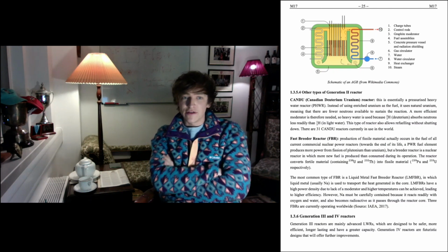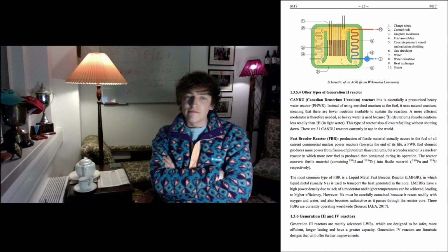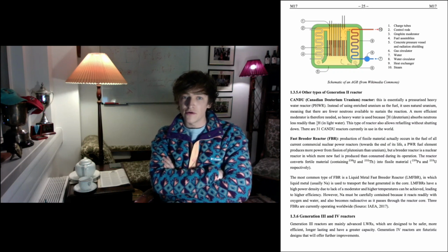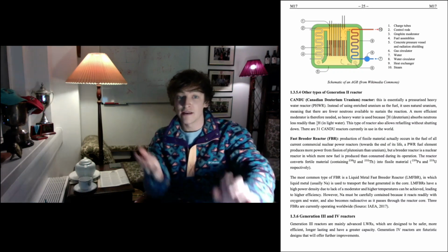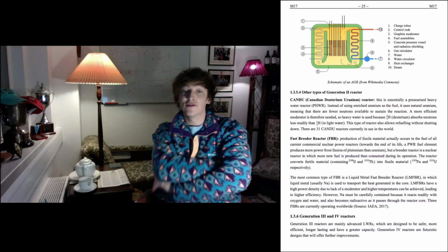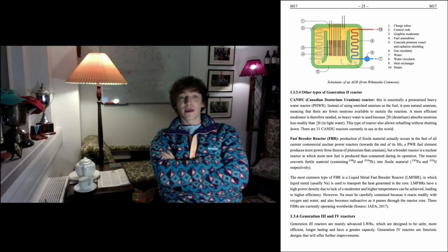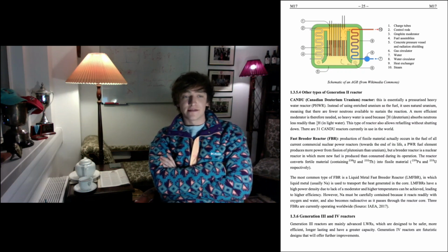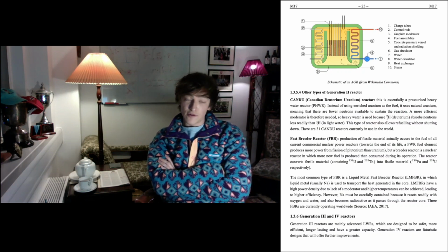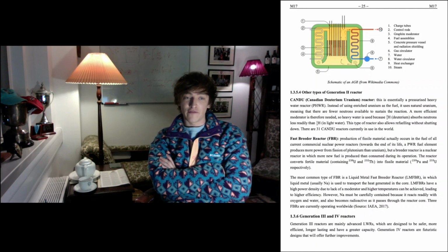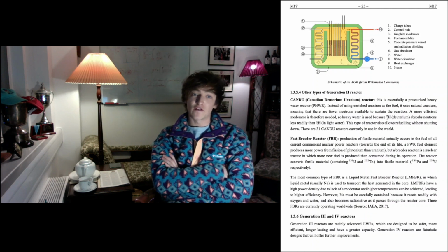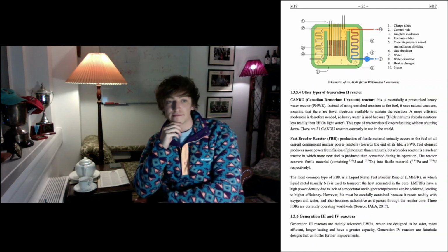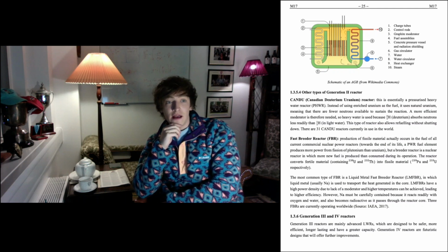And in the schematic that I've given you, you can see you've got a concrete pressure vessel around the core and the heat exchangers, all within a single pressure vessel, which is different to what we've seen before. Again, it's like the Magnox, but it's different to our water reactors. But we use water in the secondary circuit, like our other reactors, with CO2 as just the primary circuit coolant. So really, those are the most prominent Generation 2 reactors.